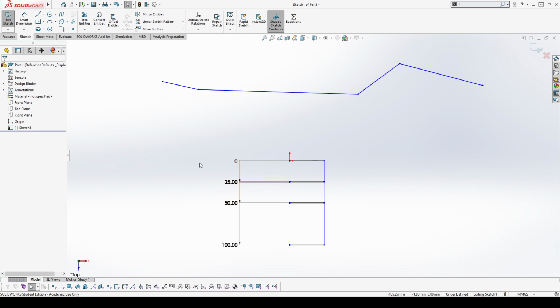If I'm making a bolt pattern and the bolts have to be spaced out every so often. If you've ever used a mill before, you're going to have a digital readout. And then you set your origin, and then you go over, you travel 25 millimeters, drop down a hole. And then instead of just dimensioning, oh, hey, go another 25 millimeters, the machinist then has to do the math as well. They're probably just as lazy as we are with basic arithmetic, and don't want to go through and be like, all right, 25 plus 25, that's 50. Okay, cool. I'll have to go to X50 and then drop this hole down. And we can do,